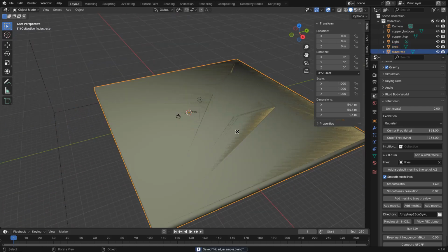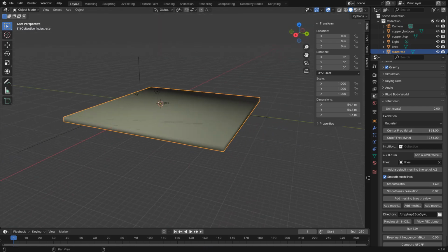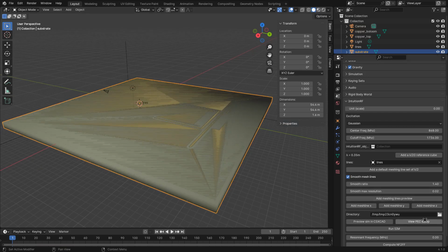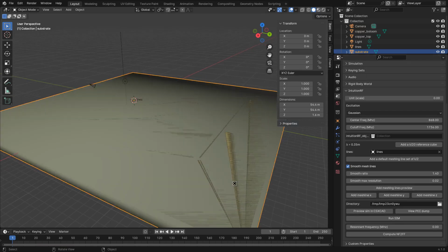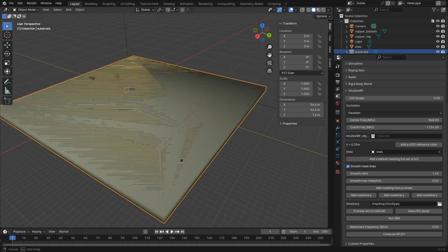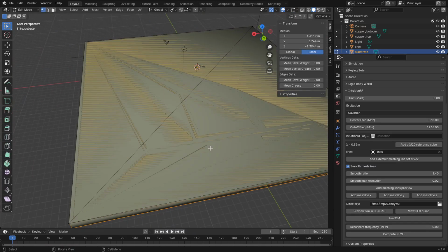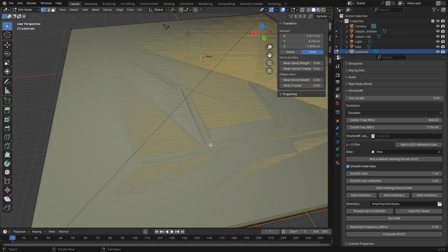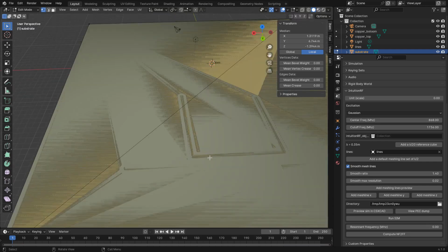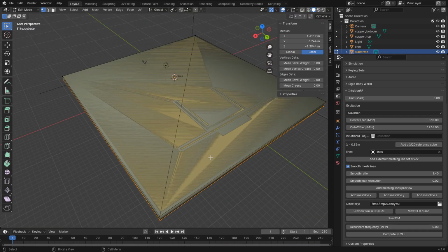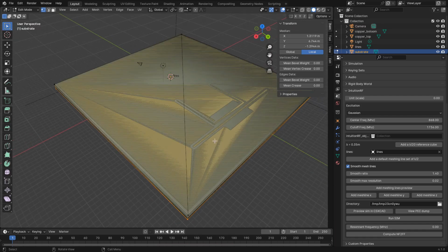And now for the meshing, this is where you actually want to use vertices on the meshing domain here and not anchors in your PCB. The reason for that is that you may have vertices that are close but not exactly the same coordinates, and you don't want to have automatic anchors be very close but not overlapping each other exactly, because that will make very small cells and will lead to a very long simulation time.